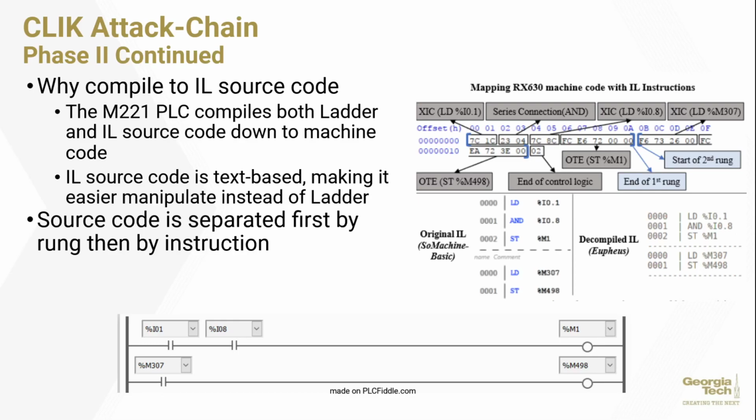So here's just a more detailed overview of what's happening behind the mapper. Machine code comes in, and out come these instruction list source code instructions. So I included this ladder logic example here, which is just the same thing that's going on with this instruction list instruction.